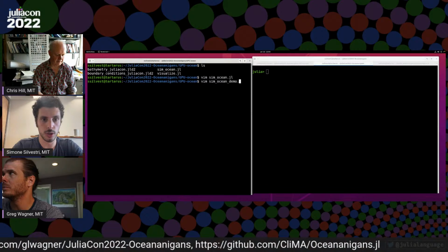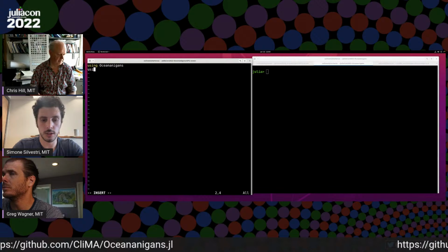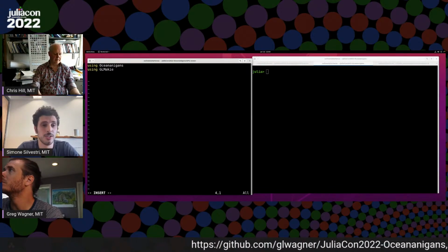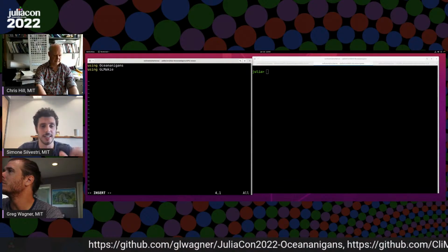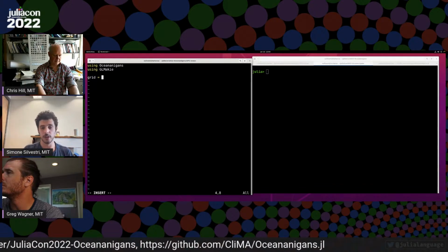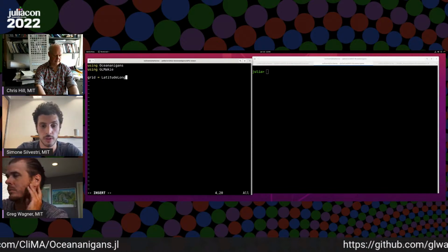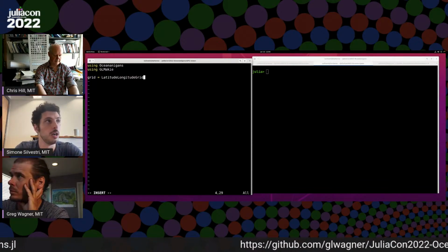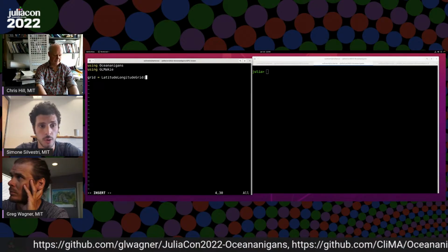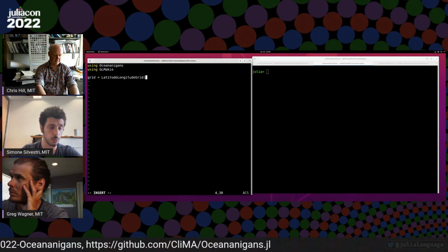Let's do OceanDemo.jl. So, using Oceananigans and using GLMakie. Let's go like this. First of all, we need a grid to simulate the ocean, but this time a rectilinear grid is not enough, because we need to discretize the sphere. So Oceananigans for this has a LatitudeLongitudeGrid. This grid will have, instead of the Cartesian x and y directions, the longitude direction on x and the latitude direction on y.